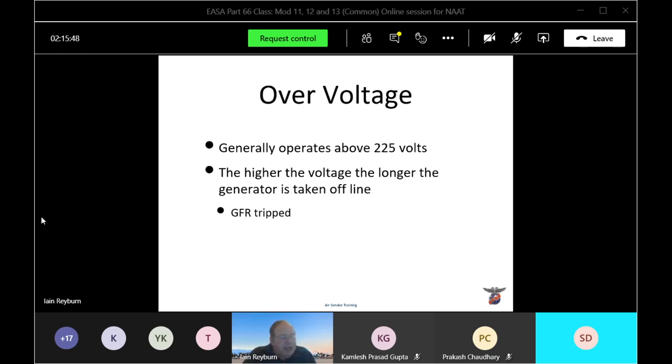And remember, gentlemen, what did I say also happens when we remove the generator excitation field? What else also happens at the same time? Can you remember? Line connector disconnect. Yes, exactly. We open the generator contact breaker. Those two, whether it's AC or DC, are exactly the same. We remove it, open the field, remove it from the distribution system. So open the generator field relay and open the generator contact breaker.